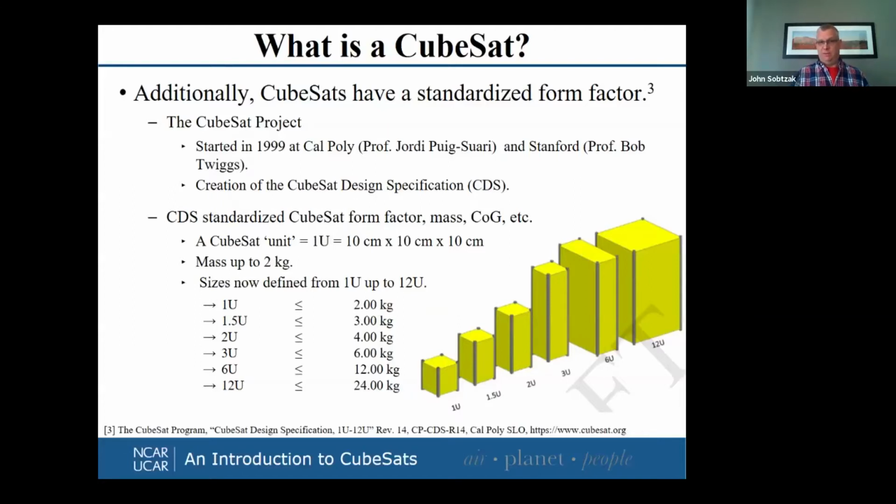There are now CubeSats all the way from 1U up to 12U. Basically, they started taking the 1Us and stacking them. Well, that's a 2U, that's a 3U, let's put those together, that's a 6U. There are 24U satellites I've seen in design stages. I don't know if any have flown. But the big point is they formed the standard that defines what a CubeSat is. This allowed people to develop launchers, and everything is of the same size. So everything was very standardized and makes it easier for other parts to be developed.